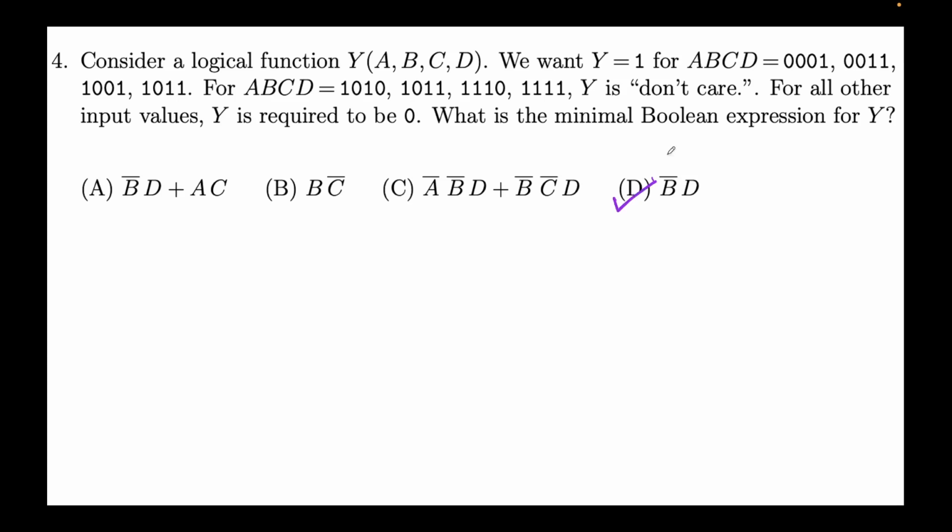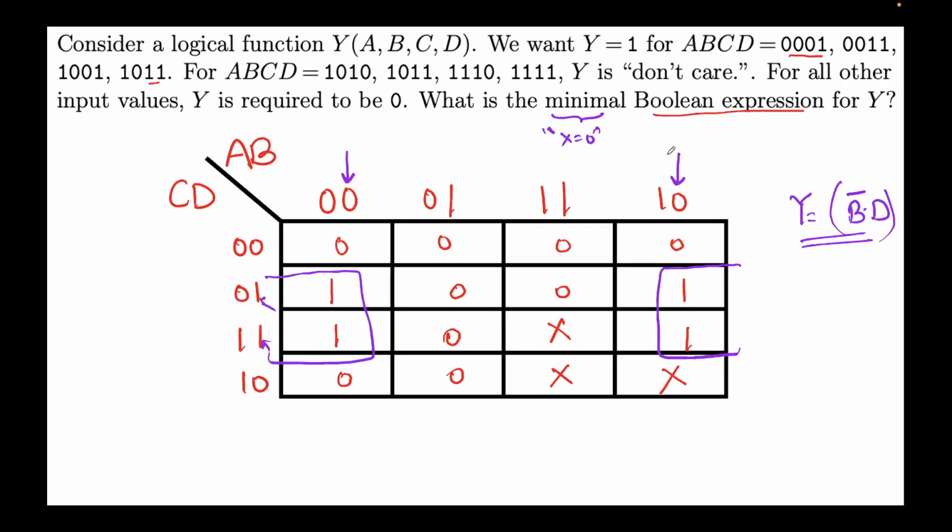All right. So that's how we approach the same problem using Karnaugh maps. Okay, I'll just summarize this again. First of all, we make a table like this. There are 4 inputs A, B, C, and D, so there must be 16 cells. We populate the inputs on the top and on the side of the table such that only one of the inputs can change when we jump from one column to another. Here you see B is changing, from here only A is changing, and then again only B is changing, and from the 4th column to the first column, only A is changing.